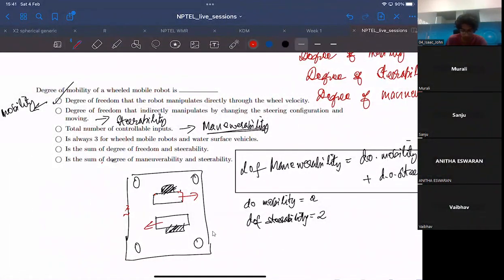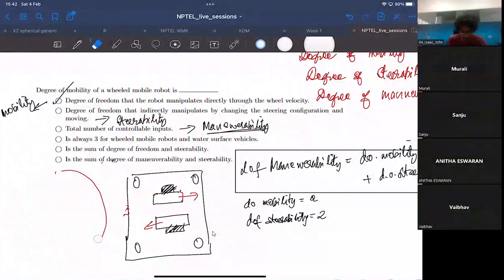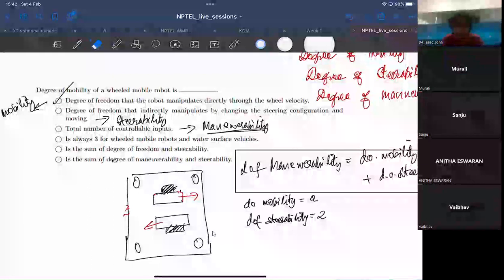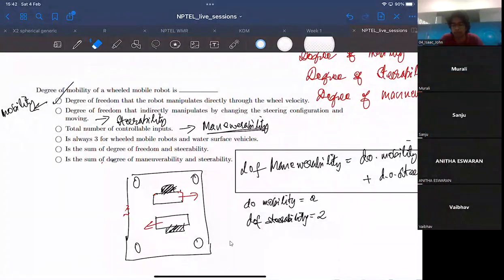Exactly the right point. If you want the robot to move in a circular trajectory or something like that, I suppose differential action would still suffice, right? Yeah, differential would suffice, but you're saying that there might be a case where you need 2 independent steerable options. If you have 2 independent axes running front and back, then you can steer them independently and make a well-defined path. Hopefully, we'll come across such examples in the next week's lectures. If you raise this question, I can have an informed look on my own, and I can get back to you.